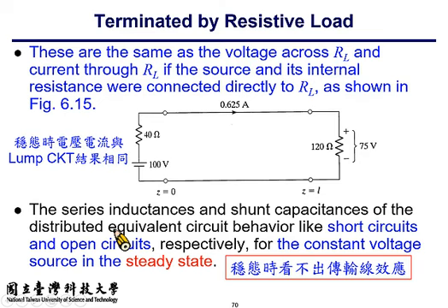All right, so here is a simplified illustration of the transmission line circuit, providing that you observe the signal for a sufficiently long time. That is the steady state circuit. As you can see here, the transmission line component is eliminated in the steady state, and the result is the same as lumped circuit analysis.